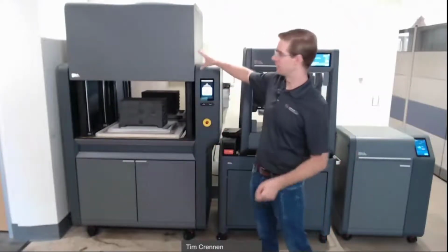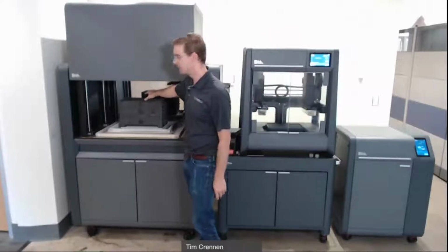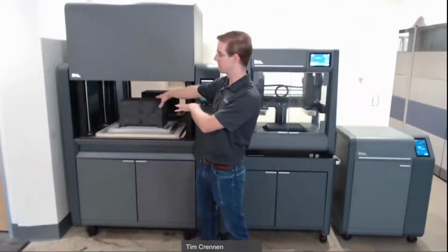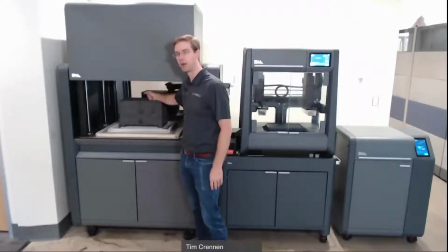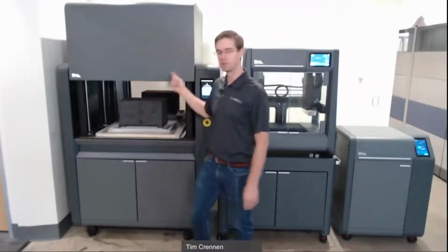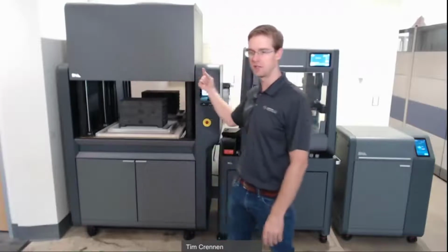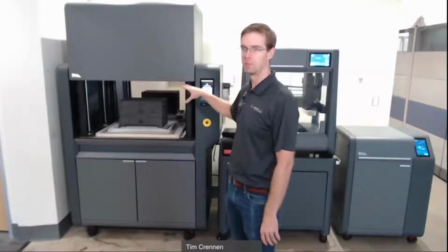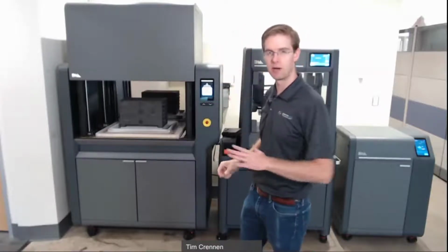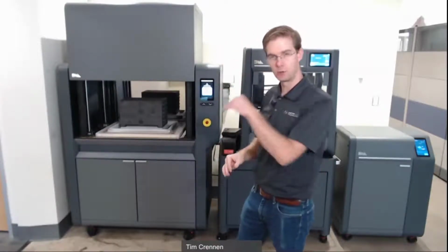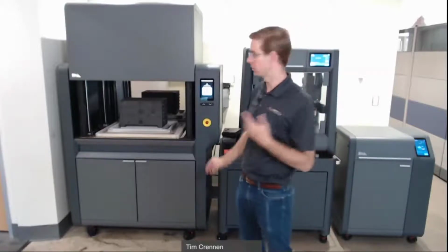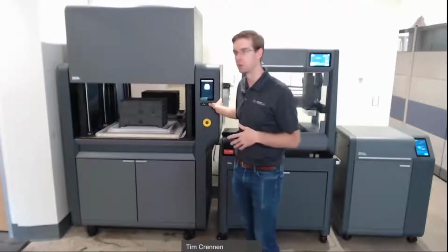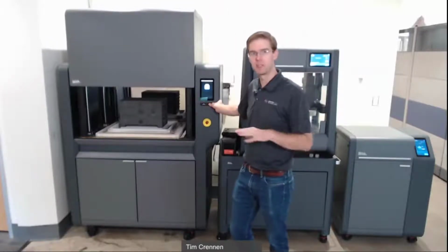So here's the furnace. All the parts fit in here, and again, it's going to be batch processed. You take your parts and you set them on ceramic setters inside our graphite retort. Then it has a bunch of high temperature heaters in there, and we run that. That takes about a 48 hour procedure to run through the whole sintering. It ramps up the temperature, then controls the cool off. Actually, the whole thing is run under an inert gas combined with vacuum, depending on which part of the cycle it's in.